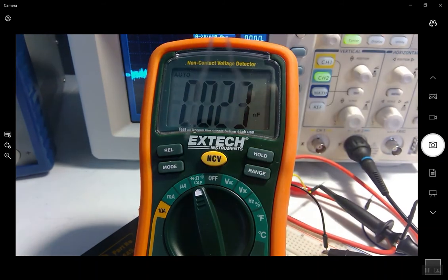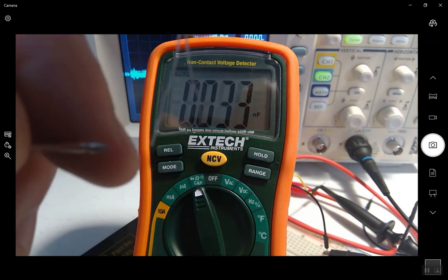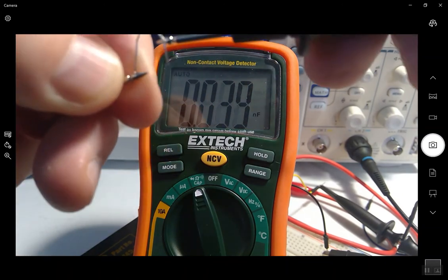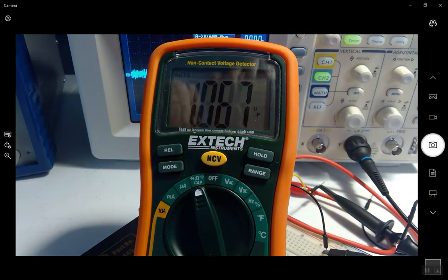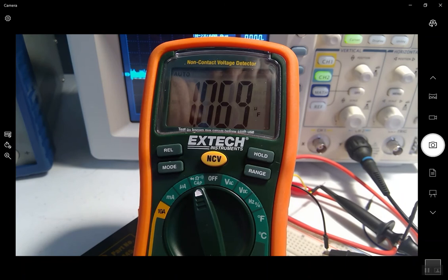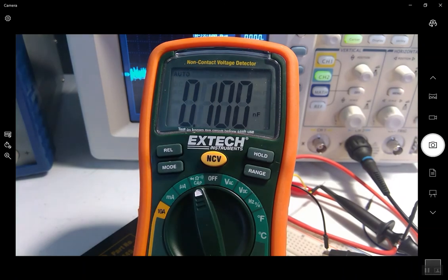The other thing is, if you look here on these leads, the positive lead is always longer. So I'm going to touch them together like this. And this time I'm reading 1.071, or 1.074 microfarads, but when I measured it earlier, it was at 1.053. And so you want to use those actual values to compute your time constant, because we want to be able to look at it and see if we can measure that time constant and get the same thing.